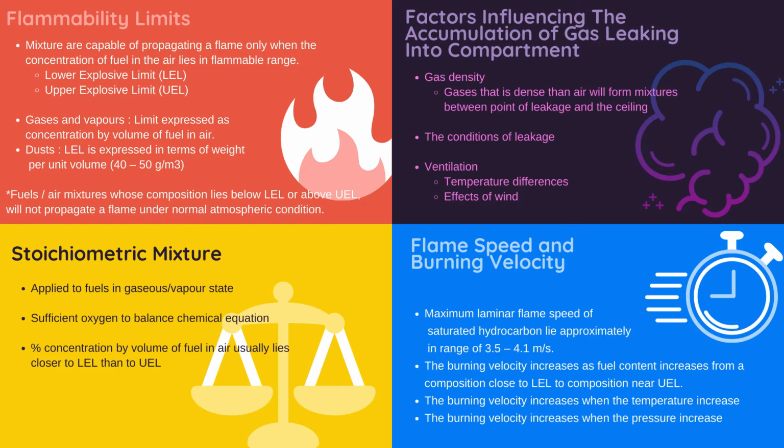There are three factors that influence the accumulation of gas leaking into a compartment. Firstly, gas density. Gases that are denser than air will form a mixture between the point of leakage and the floor. Next, the condition of leakage. Finally is the ventilation. In ventilation, the temperature difference and effects of wind will influence the natural ventilation.